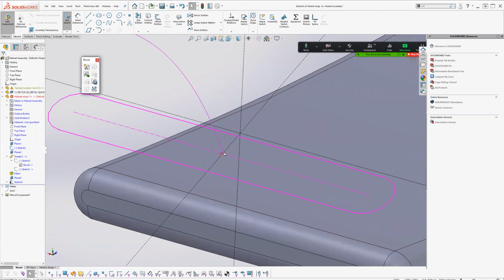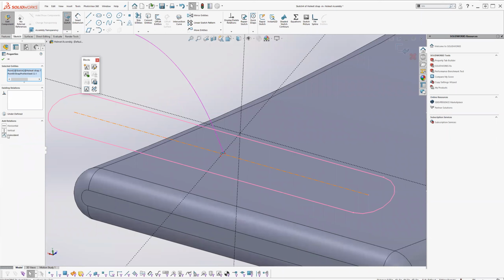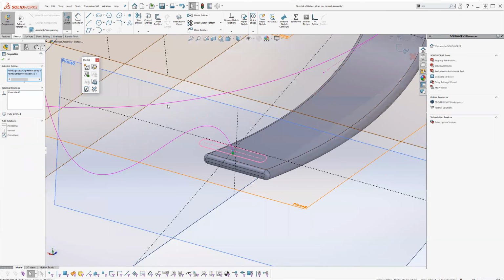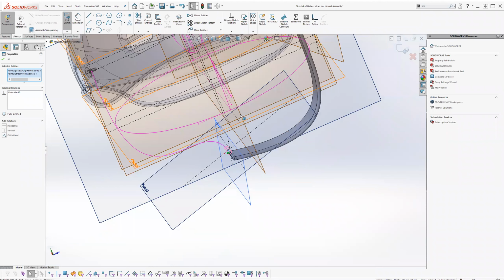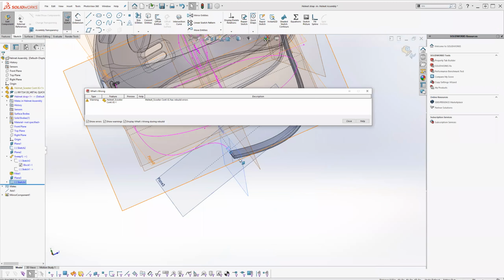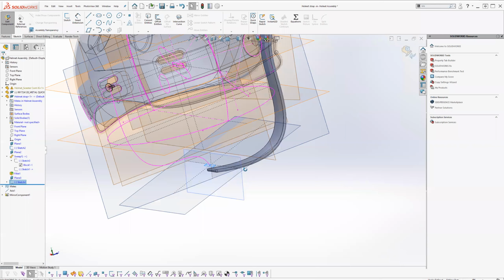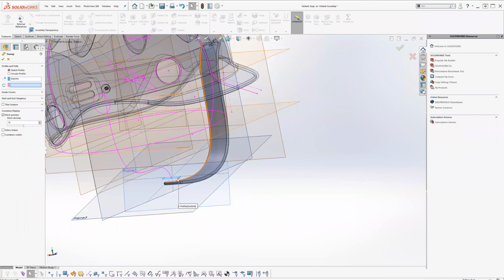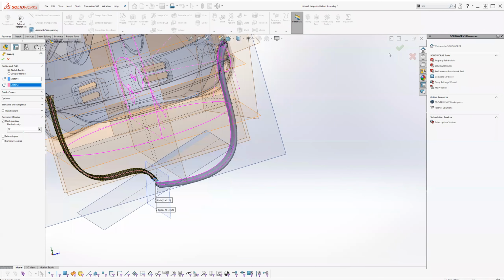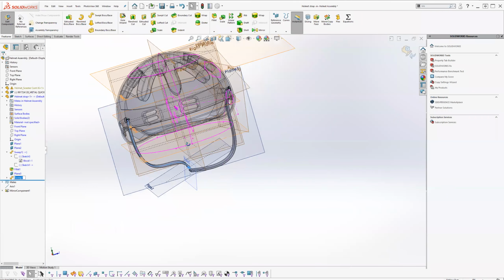There's a center of the block here, and I'm just going to make a coincident relation to it. That way it's the exact same thing that you have in another sketch. You place it in a new sketch. You don't have to keep making these, because it could be the same profile for multiple straps or something. Okay, so there we go. Same thing. So swept surface, there's my profile, there's my path, and then there you go.